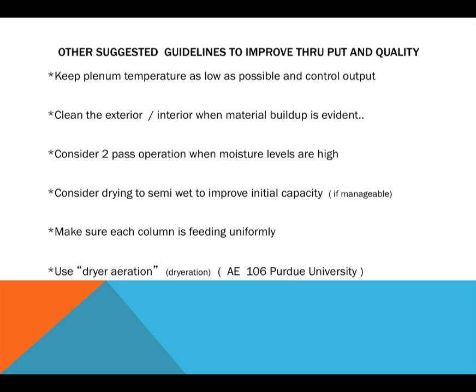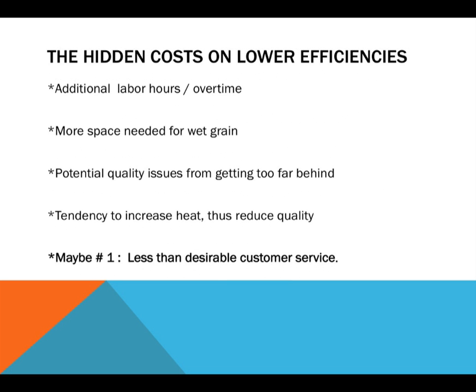Okay, leave the air off, let it sit there and steep. They have a recommended period of time. I think it's somewhere in the neighborhood of 18 to 24 hours, and then turn the fans on, blow that out, and you might gain yourself a point and a half, maybe 2 points, depending on what you're doing there. It could improve the put through to the dryer, take some of the pressure off of you having to keep raising the plenum temperature, when you're trying to dry.